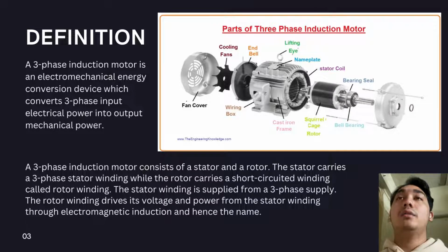Three-phase induction motors are the motors most frequently encountered in industry because they are simple, low price, and easy to maintain. Such machines are called induction machines because the rotor voltage, which produces the rotor current and the rotor magnetic field, is induced in the rotor windings rather than being physically connected by wires.